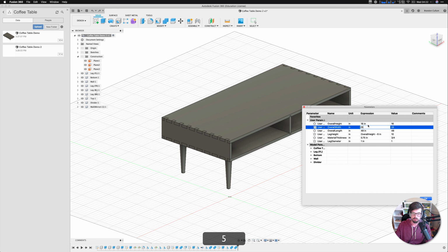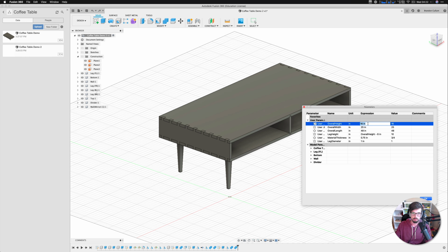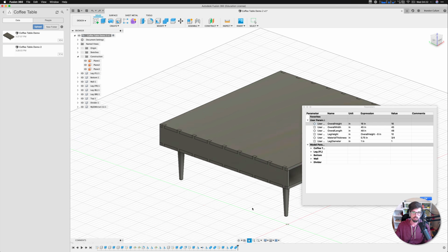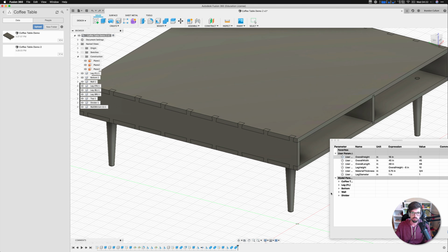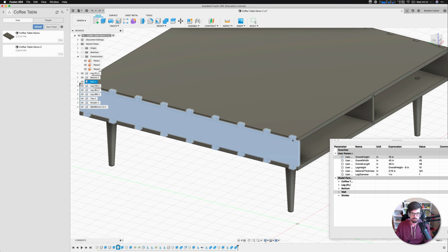Now, if you remember, the width is going to be a little bit different. Since we typed in just a hard number for the dovetails, the spacing is going to get kind of crazy. So what you could do, if we're making something massive like this, is go back into this feature, which is down over here.